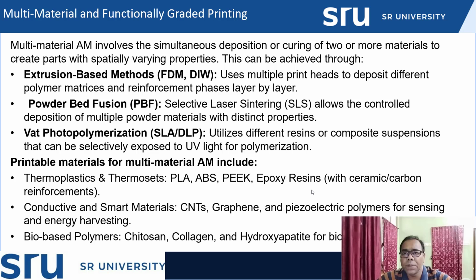So in multi-material and functionally graded printing techniques, more than two materials are used, and layer upon layer printing takes place in all additive manufacturing techniques. Certain layers will be printed with a certain functionally graded material, so they will behave differently compared to other layers. Certain layers will have higher mechanical properties, lower mechanical properties, or maybe some smart properties